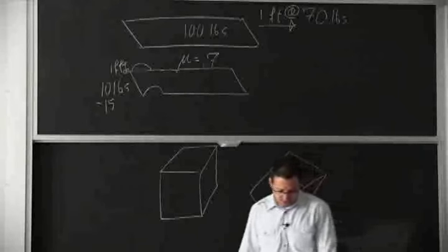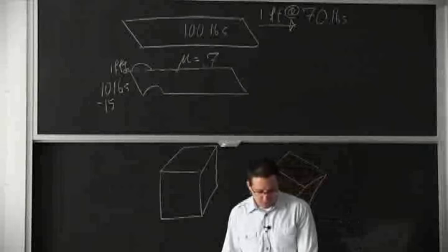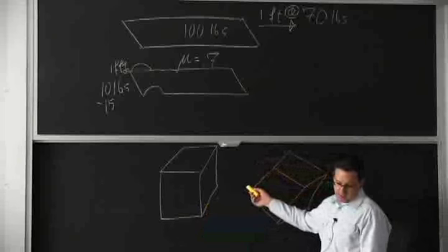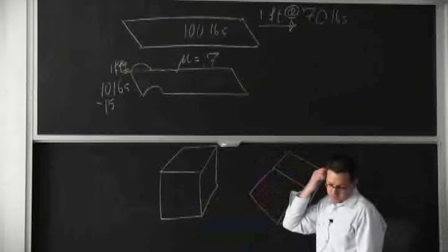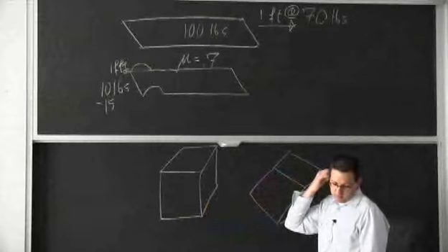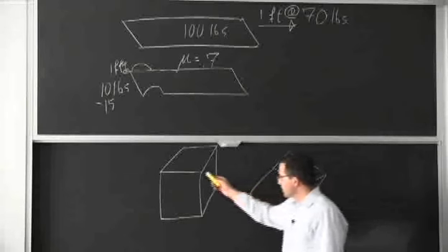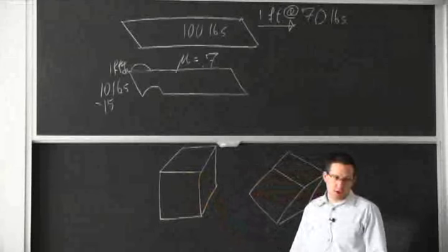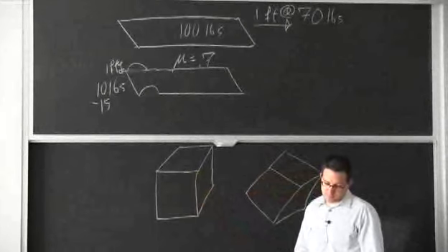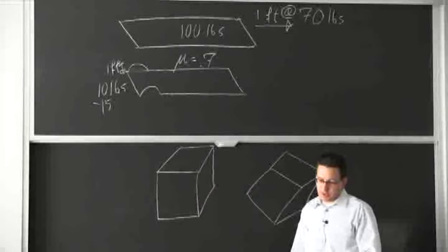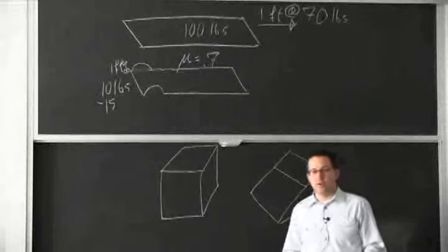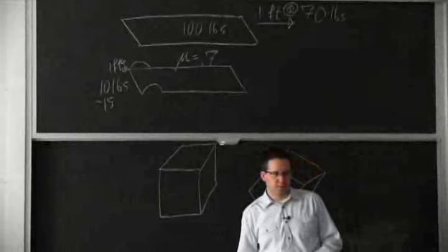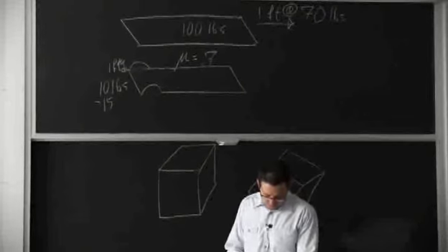So the principal stresses, the equations are at the bottom, because you have 3 I values that you determined from any of those boxes. Pick any of them. So you use equation 1.11 with any stress coordinate system. It gives you I1, I2, I3, and then you use the 3 other equation 1.12 to determine the principal stresses, so sigma 1, sigma 2, and sigma 3. And it works.